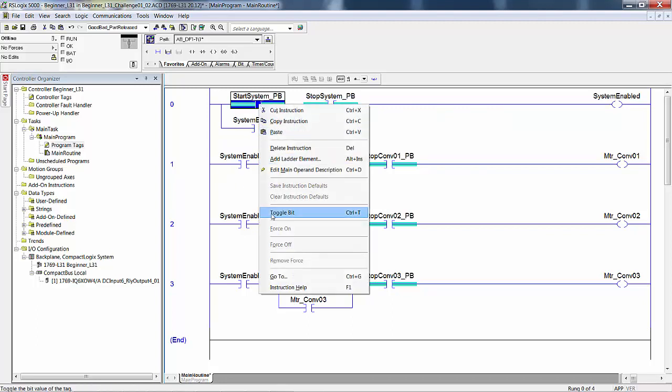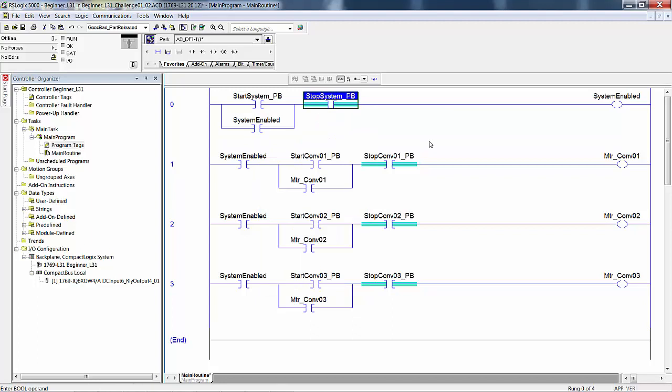We'll save that and we'll do that again. We're offline right now, so it really doesn't work. We will probably not have you exercise your logic by toggling bits in the memory again after this instance. Since we do not have our tags aliased to field devices, I/O that is, we will exercise our logic by toggling memory locations. I am going to have you download it.